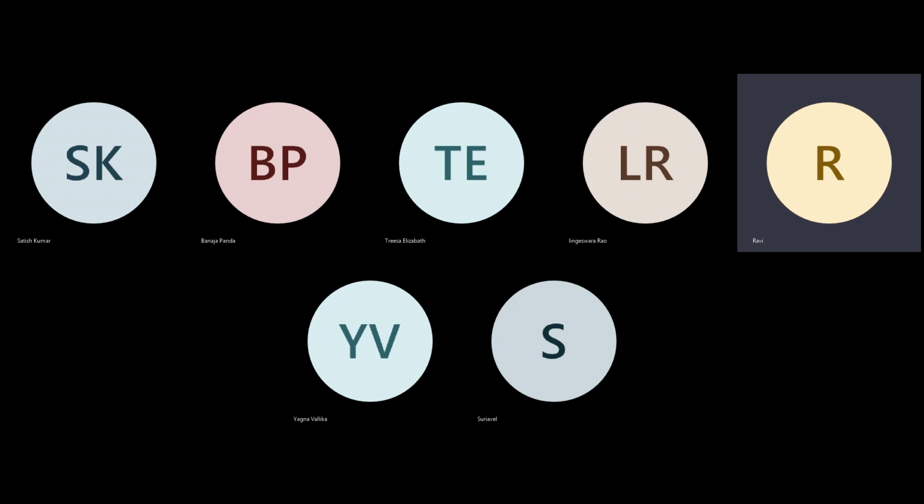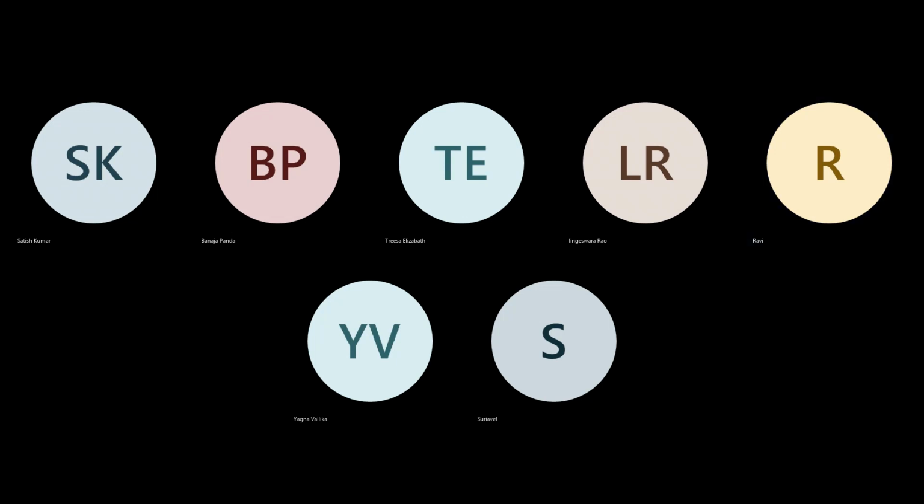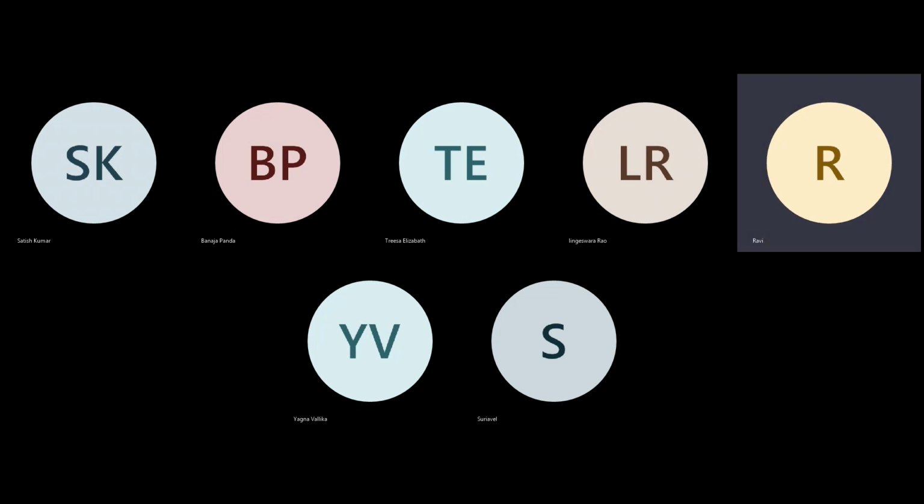So when you're doing macro placement, the general philosophy is you have to understand what your block is supposed to do. Where is your architecture? Where are your inputs, where are your outputs? That means where are your input ports and output ports? How is the whole module talking?